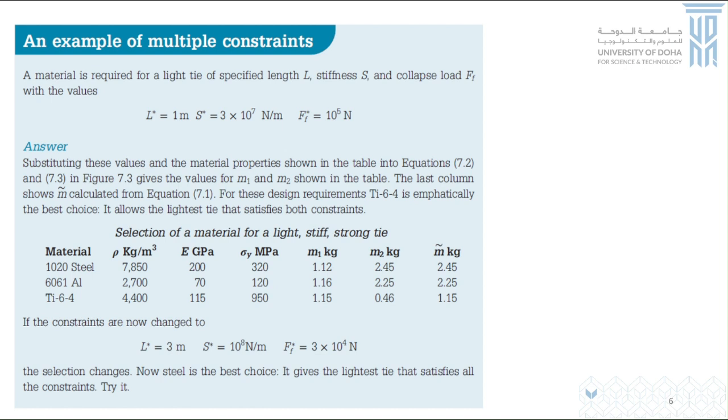Can't we plot the values in a graph to see it visually more easily? Yes, we'll do that later on, but right now it's only 3 numbers, so it's just to give you a physical appreciation of the numbers. We'll do the graphical method later. But what I'm trying to explain here is the limitation of using the performance function of the mass directly to minimize. What the material index does is decouple the geometric part from the material part.